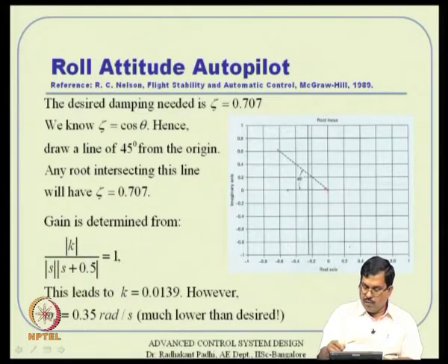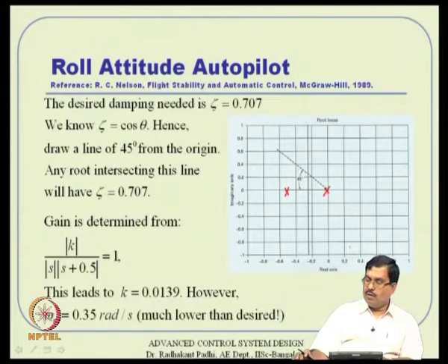This is one pole at the origin, and one pole here, at about minus 0.5 location. So, if you apply the rules of the root locus or you simply draw it using MATLAB and things like that, the loci will start from the poles, they will go that way, and then ultimately they will meet here and then they will diverge this way. That is the root locus actually.